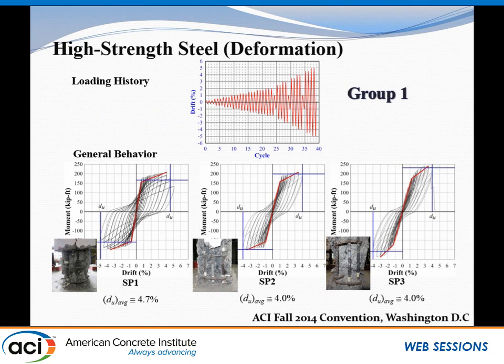This is the hysteretic response between moment and chord rotation of the first group of specimens. Specimen SP1 failed due to severe buckling of the longitudinal rebar. Specimen SP2 failed due to fracture of one corner bar and buckling of the rest. Specimen SP3 failed due to fracture of all 3 reinforcing bars.